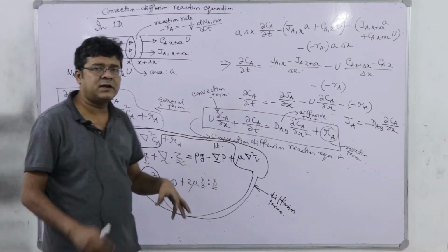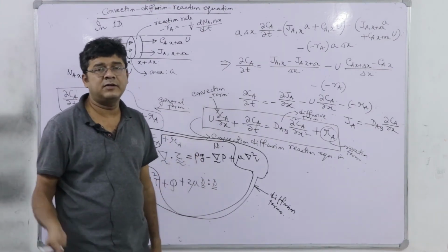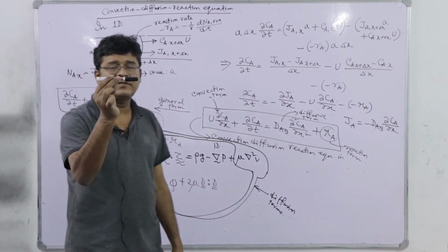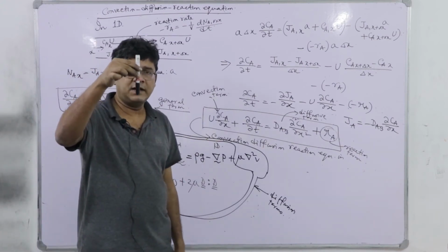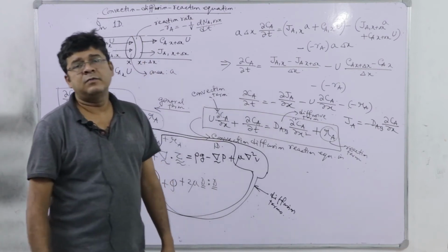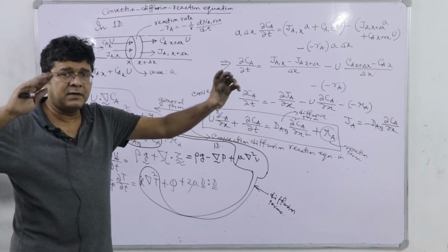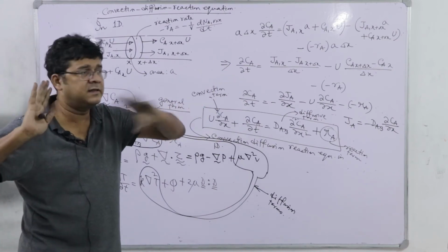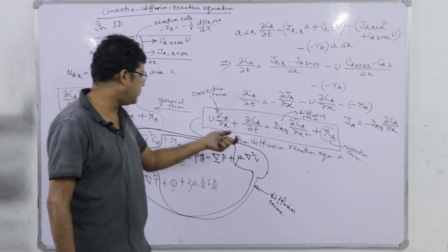Here you see momentum can be generated by changing the pressure, applying a pressure gradient, or applying gravity. If I have a straight pipe filled with liquid, and I put it vertically down, by gravity we have the generation of momentum. Alternatively, for a straight pipe, if I apply a pressure on the right hand side and keep the left hand side opening at atmospheric pressure, the momentum will be generated.